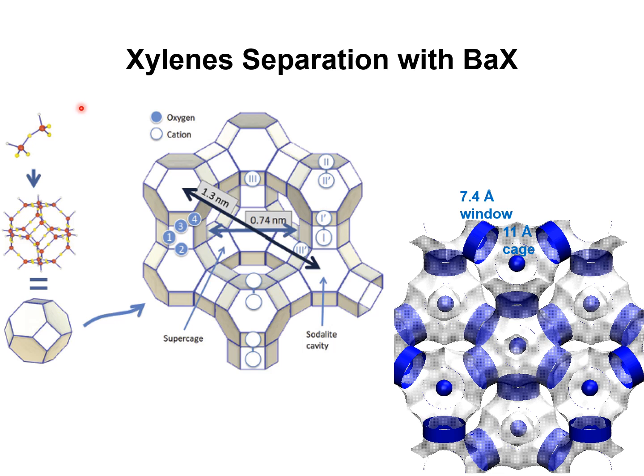In current industrial practice, the adsorbent used in simulated moving beds is barium X-zeolite that has the faujasite topology that consists of cages of approximately 11 angstrom size that are separated from adjacent cages by 7.4 angstrom windows.